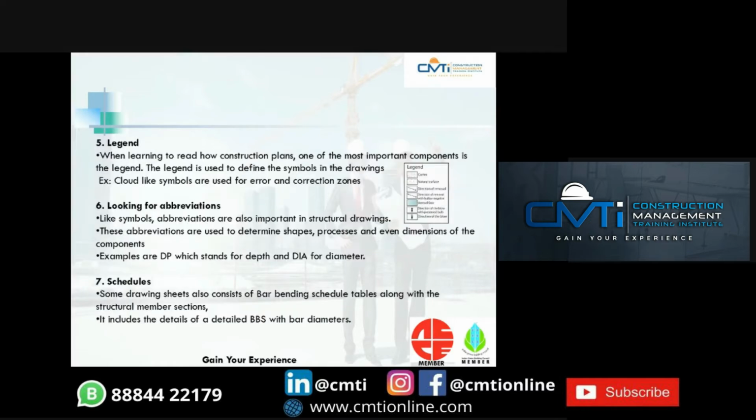The fifth one is the legend. When learning to read construction plans, one of the most important components is the legend. The legend is used to define the symbols in the drawing. So beside is a legend, there you will see the symbols which are used for various purposes. For example, cloud-like symbols are used for error and correction zone. And the sixth one is abbreviations.